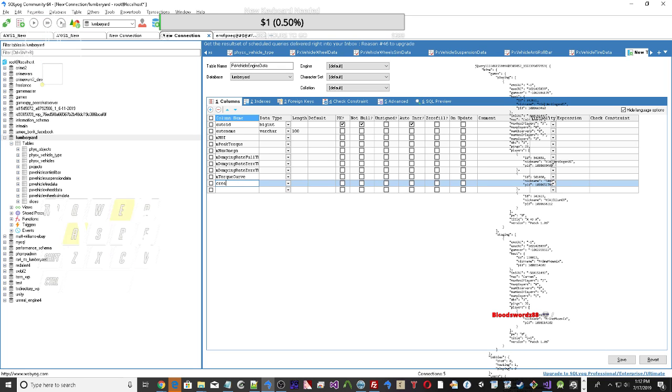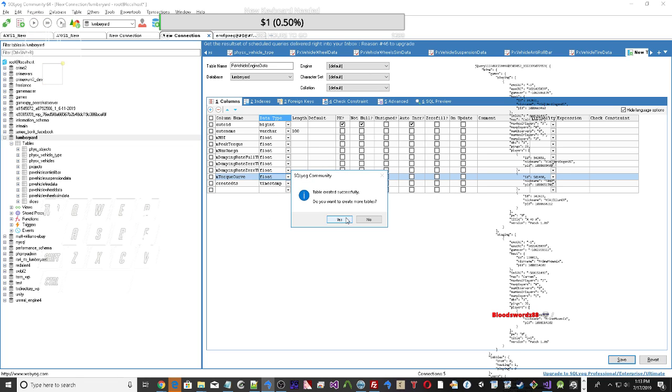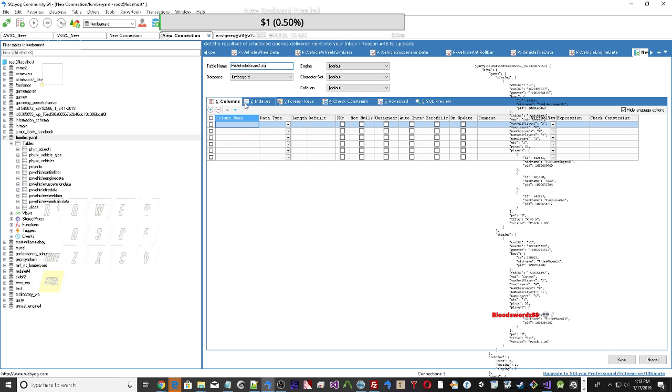Algorithm. The Physics Vehicle SDK models vehicles as collections of sprung masses, where each sprung mass represents a suspension line with associated wheel and tire data. These collections of sprung masses have a complementary representation as a rigid body actor whose mass, center of mass, and moment of inertia matches exactly the masses and coordinates of the sprung masses. This is illustrated below.